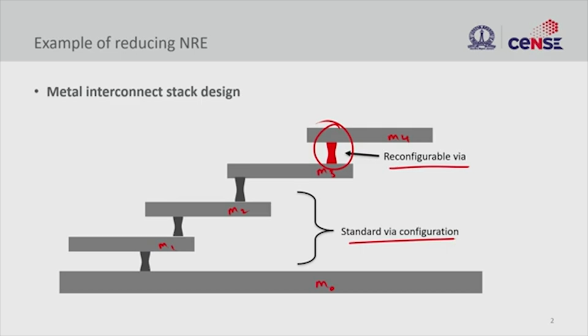This allows you to reduce the cost of releasing a new product or realizing a new device. It's not just the cost, but also reliability, because you are not changing all the metal layers and all the interconnects. You are only touching one layer. So this also tremendously improves your yield when you go from one device architecture to another, while keeping your back end or interconnect architecture relatively stable and standard.